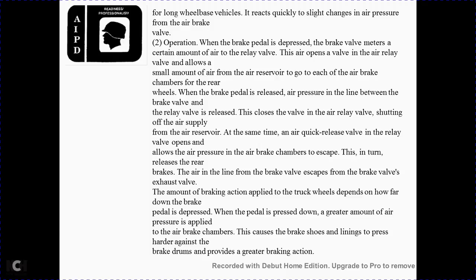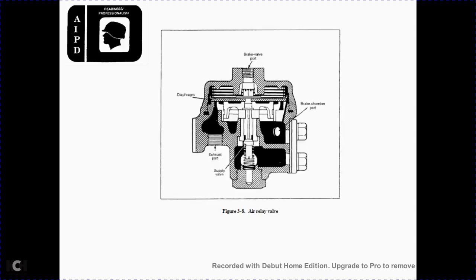The further the pedal is depressed, the greater the amount of air pressure applied to the air brake chamber. The brake shoe with the lining presses harder against the brake drum to provide greater braking action. Figure 3A shows the air relay valve, the brake valve port, the brake chamber port,